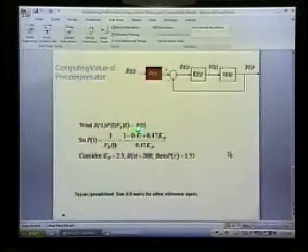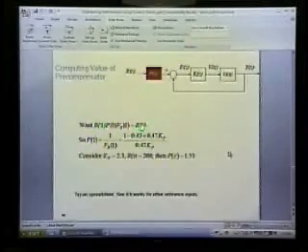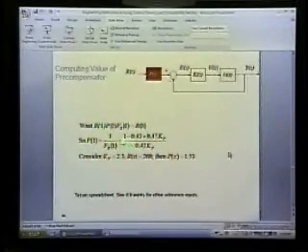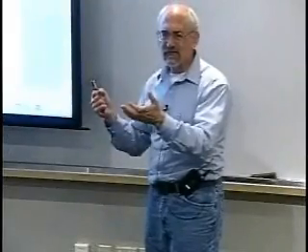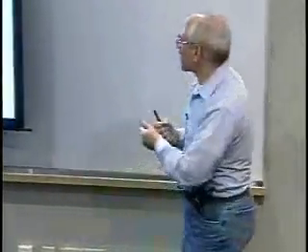I'm sorry, this is the output, that should be y. But we want it to be the same thing as r. We want this and this to be the same. So that means these two things cancel out, and the precompensator should be 1 over the transfer function. It's not surprising, right? Because we've got a transfer function that's producing 90%, and we compensate for that by multiplying by 1 over that, because then the product of those two is going to be 1. So it's sort of intuitive.